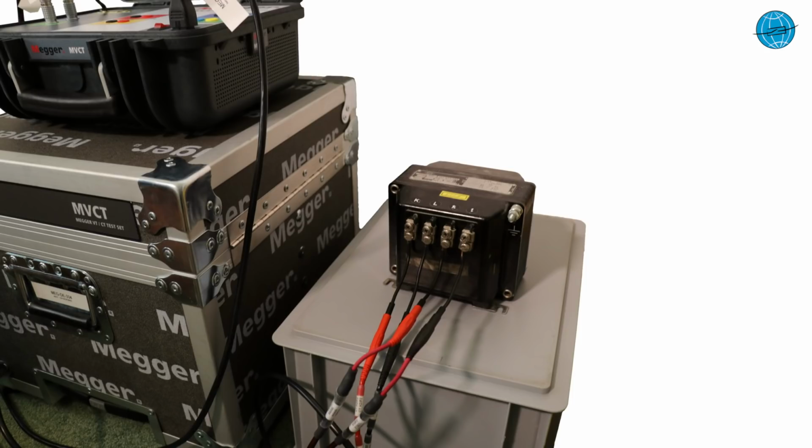Now let's take a look at the MVCT measurements and start testing again. Again, you can't go wrong. The test circuit is also shown on the device and the test cables are all clearly labeled. However, the MVCT is not connected to commercially available test leads, but with a special MEGGER connector. This has the advantage that you have to think even less when connecting to the device, but you cannot easily replace a defective test cable from the standard cable case.